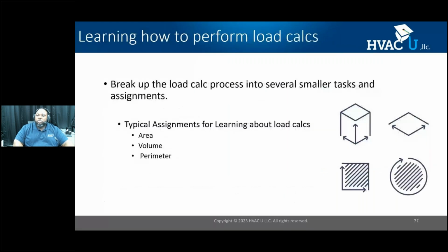Right? So when we look at load calculations, there are no rules of thumb. We have to evaluate the shell and look at the shell for what it is, and we have to do the proper evaluation, and we have to do testing with the blower door. There are no rules of thumb that will give you enough data to accurately perform a load calc. And as you see, just little inputs like adding attic insulation, if you made the replacement of a system without taking those into account, you lock that customer into the same cycle.